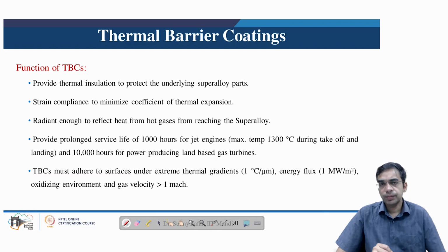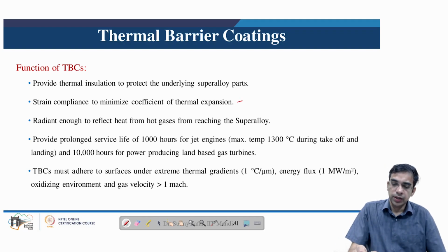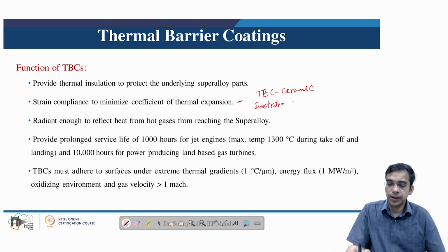The second most important function is strain compliance, to minimize the mismatch in the coefficient of thermal expansion. This point is important to understand because the TBC material is a ceramic-based material, which is applied on a substrate which is a nickel-based superalloy, a metallic material.